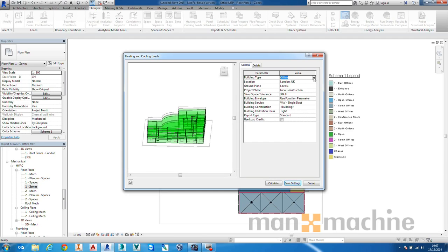Generally speaking, inside of a building you've actually got several different types of room, or in our case here, spaces. So we've got an office here, but actually within that office we might have a food preparation area, somewhere where colleagues and employees can go and eat. We might have a training room full of people and electrical equipment, and each one of those rooms is therefore going to have a different airflow and a different MEP calculation needed to get the correct fresh air intake and airflow into that space.